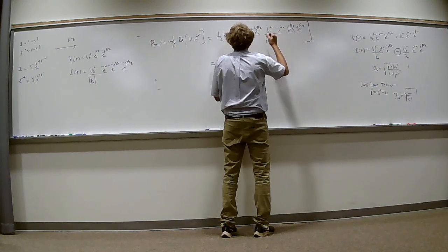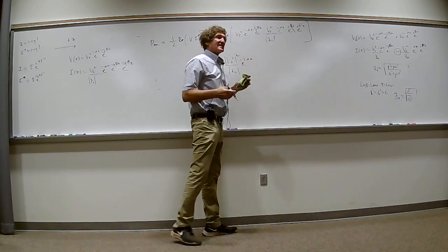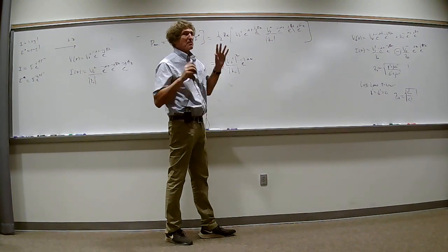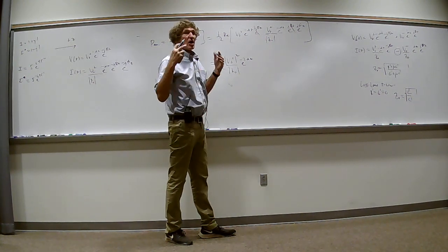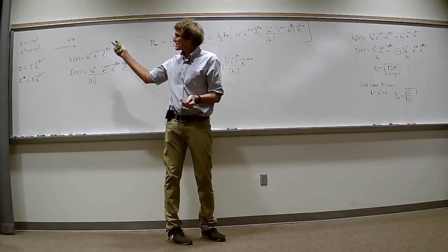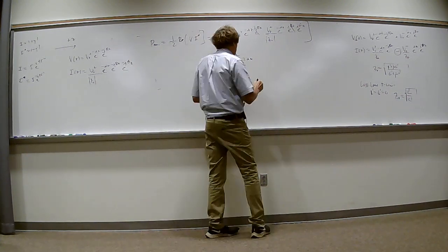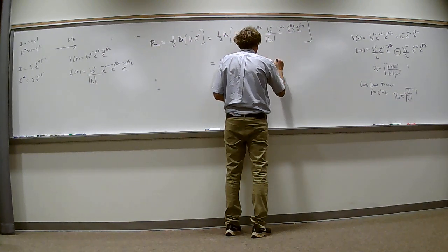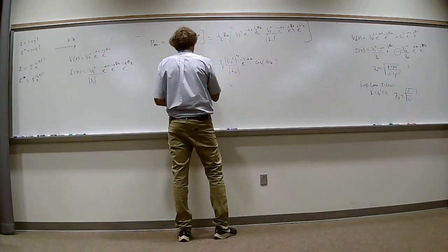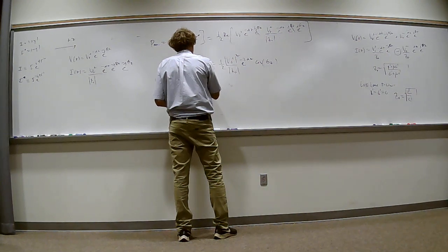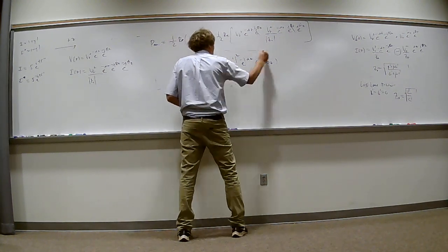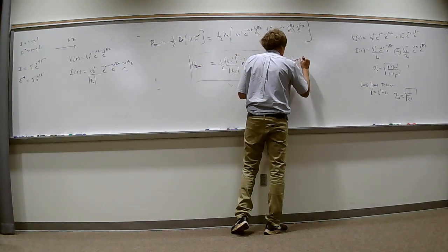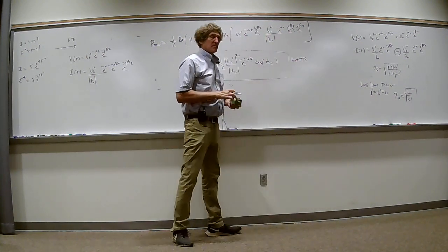Then I have the real part of e to the j theta z. What is that? What's the real part of e to the j theta, period? Cosine. Y'all remember when I had that stuff up there, right? It's simply equal to the cosine of the angle associated with the impedance. And this is the average power flow. And power flow is in watts, by the way, right? We use average most of the time.